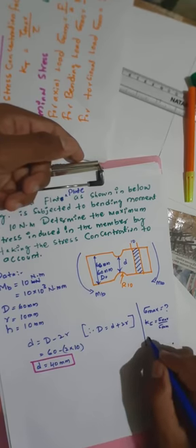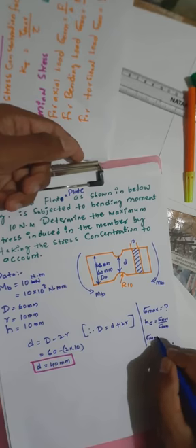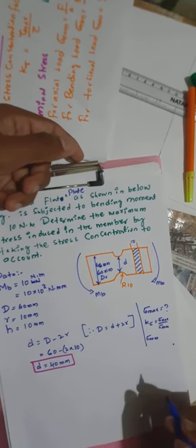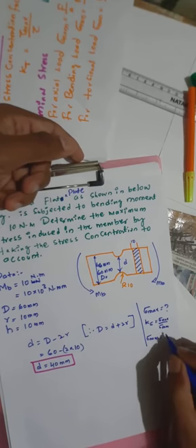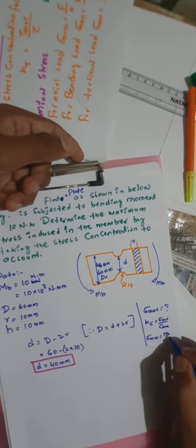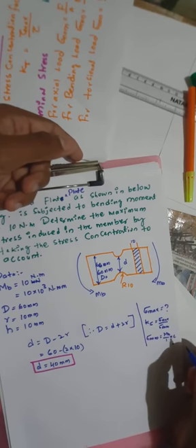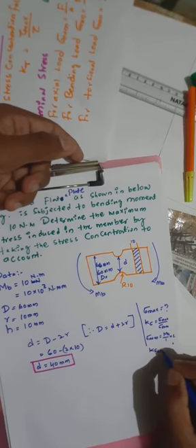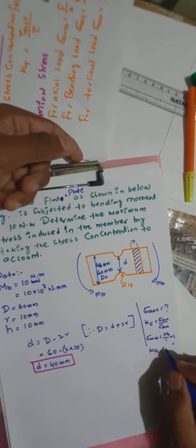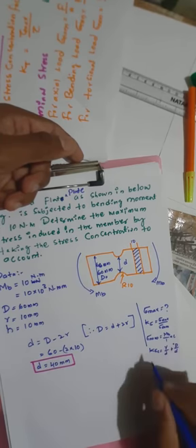Due to the bending stresses with respect to the maximum bending moment, sigma nominal is equal to MB by I into C. For K sigma we use r by d and capital D by d.